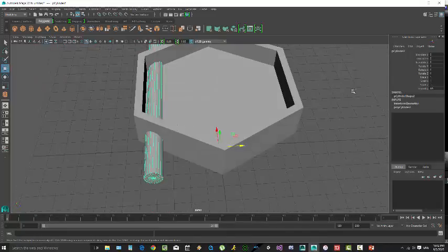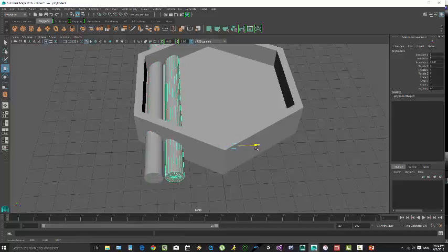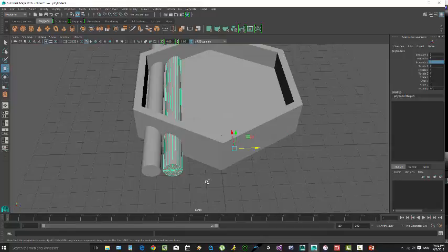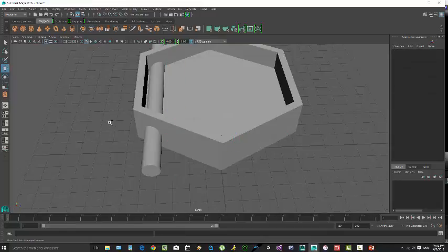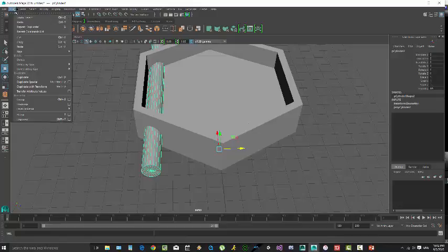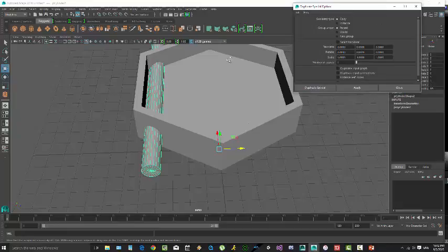So now with these transforms reset, set to 0, now I can go to Edit, Duplicate, and now when I move it, I can see the exact distance that these two objects are apart. Alright, we can just set it to be 1, nice round number. Okay, looks okay. Delete that. Now, instead of duplicating, we're going to say Duplicate Special. And when this dialog box pops up, we can change some settings, which is what we're going to do.